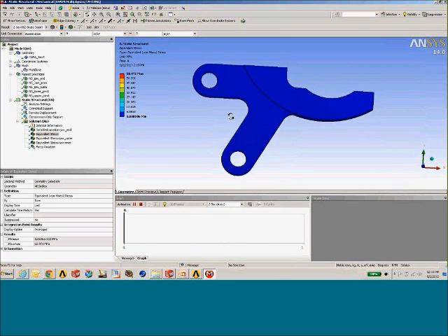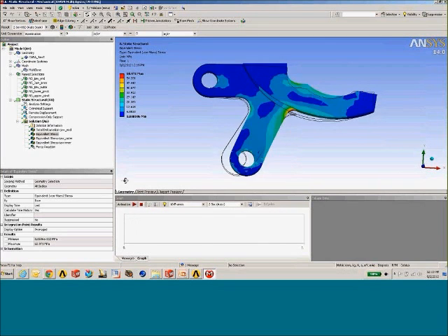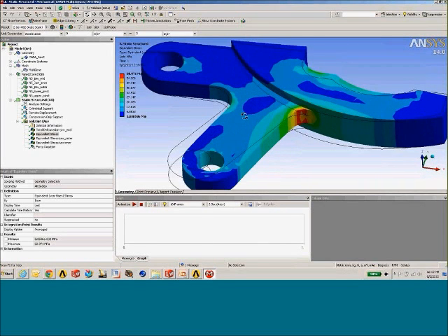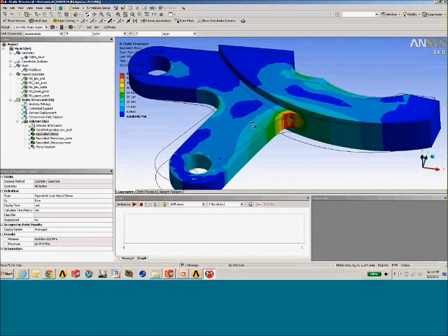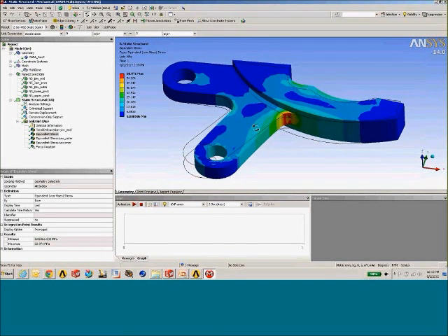Make sure that your boundary conditions make sense. Make sure that in this particular case you have a sufficient number of elements in this high stress region to capture what's going on there. So go through, do your mesh refinement studies, get the model robust and consistent for your single design point before you kick off the parametric analysis.